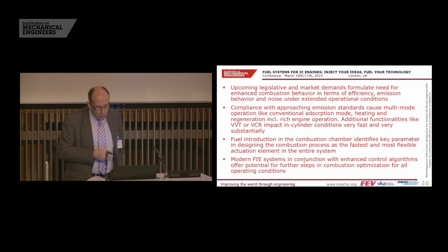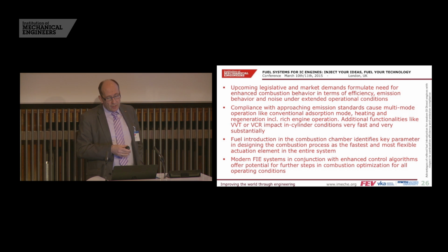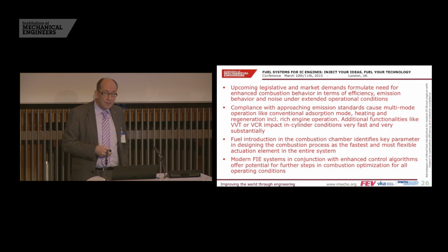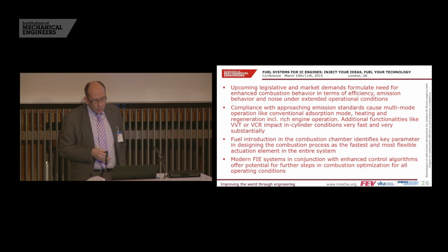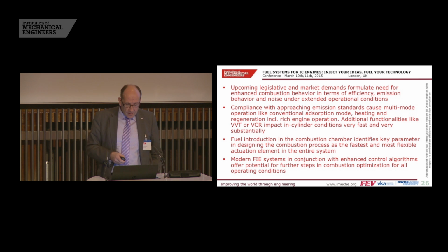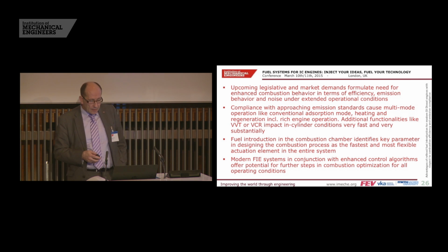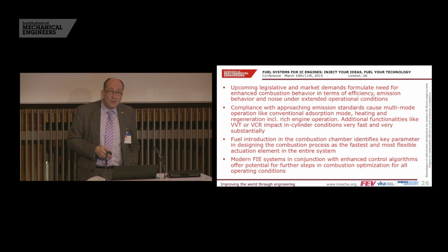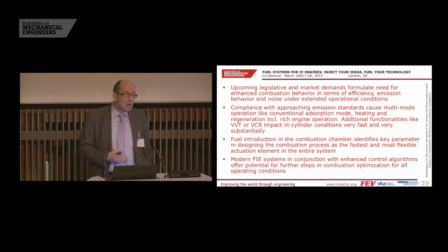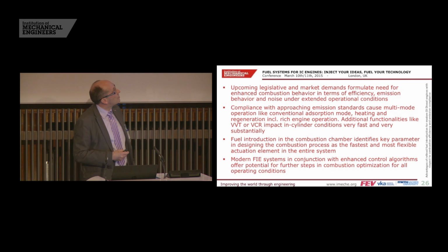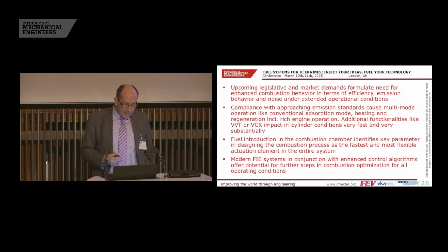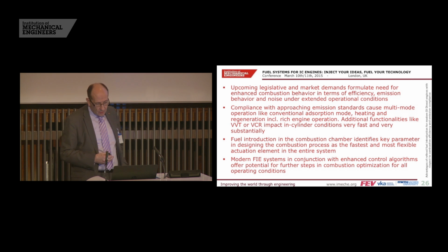The compliance with approaching emission standards causes multi-mode operation as well. So we have, of course, conventional adsorption modes, we have heating and regeneration modes, including rich engine operation, and in the future we also see additional functionalities like VVT or VCR on diesel engines, which impact the in-cylinder conditions very fast and very substantially, and where we have to react with the FIE system, as it is the fastest, most dynamic system in the engine, which can react very fast to changing boundary conditions.